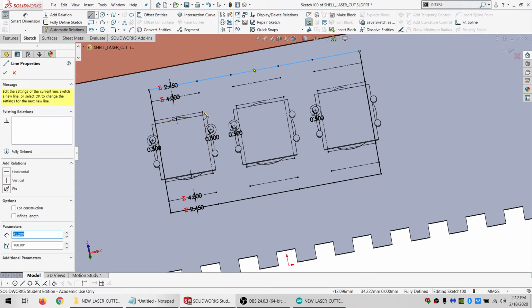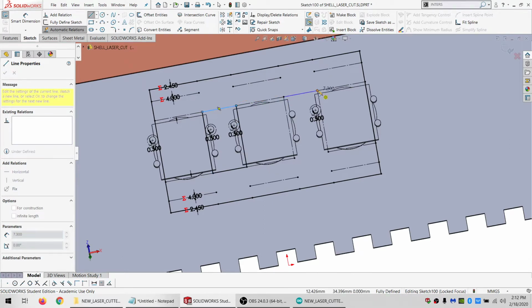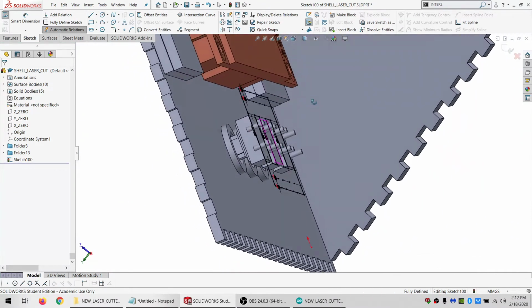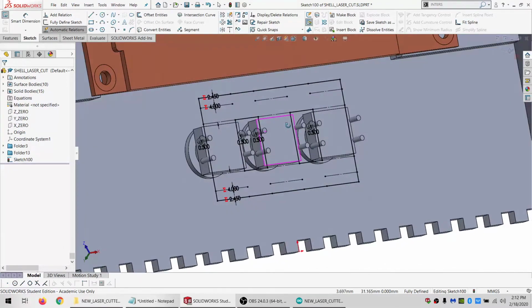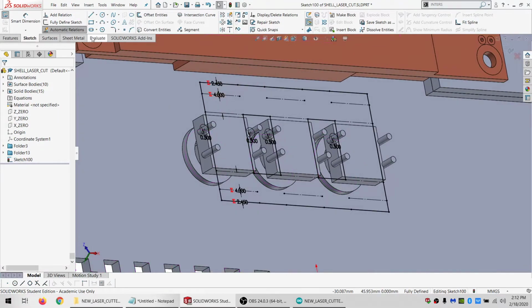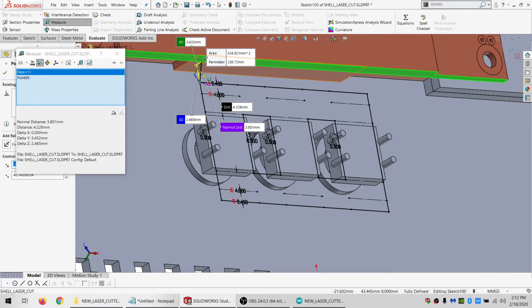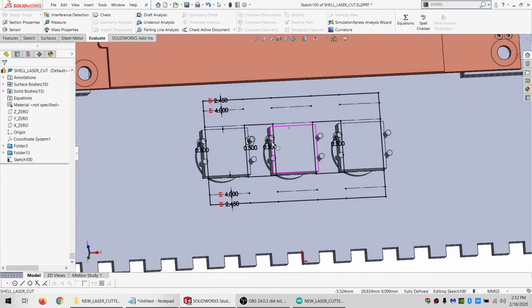And then we just need an opening for those 2 pins, and for these 2 pins, or 4 pins. And so that works. Let's just evaluate, measure from there to there. So 3 millimeters, that's plenty. Actually, I can make this a little bit bigger if I want to, but I'll leave it so if I expand that, I'm alright.